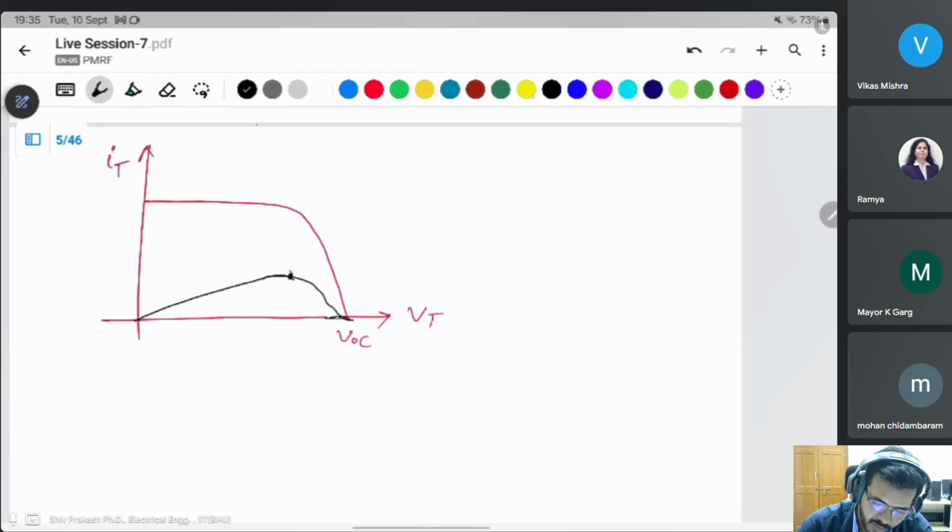This is the maximum power point. Same thing for the current, Im, and this one the Vm. If we track this voltage and current and compute the power, then we track the power and voltage to increase or decrease the duty cycle accordingly.